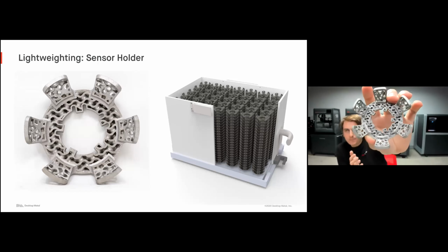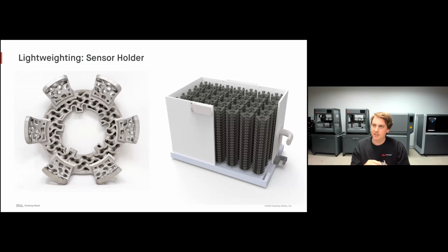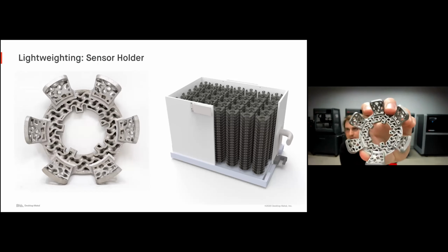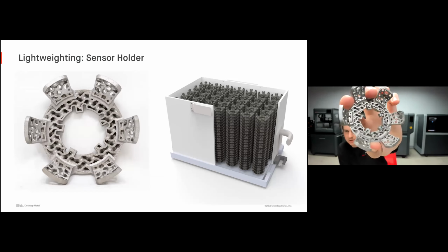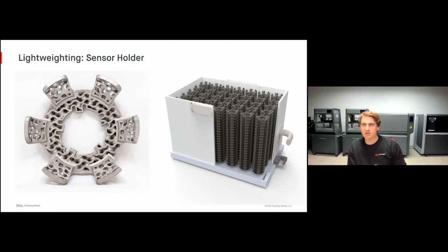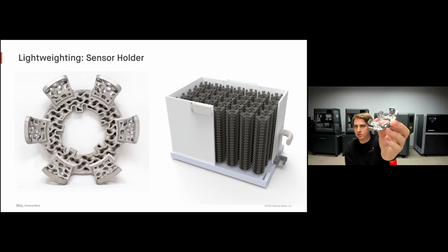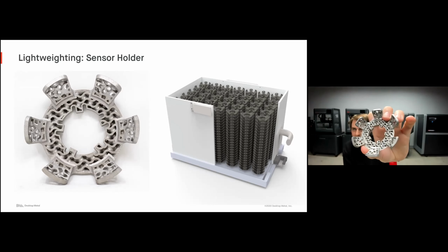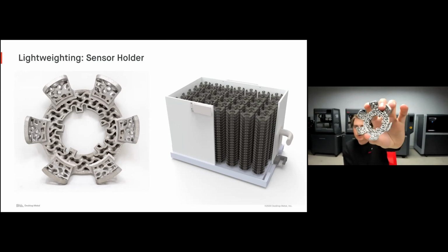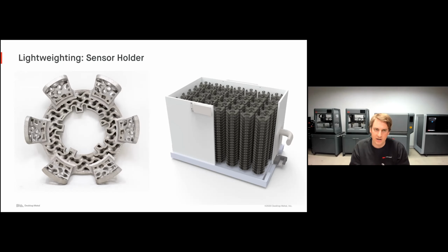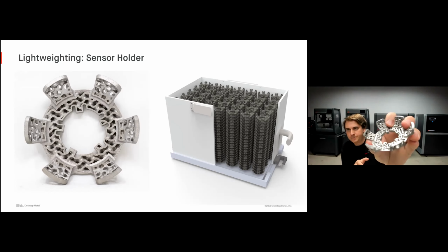Where with 3D printing, it's actually possible to increase the complexity by doing something like this and actually lower the part costs. So much of part cost is associated with material usage. So by reducing the amount of material that's being used, we're actually reducing the cost. And again, it's not just that I can now produce one of these for some special rocket ship or something like that. I can produce hundreds of these parts per day to actually go into applications that we're interacting with every day on a much lower criteria.